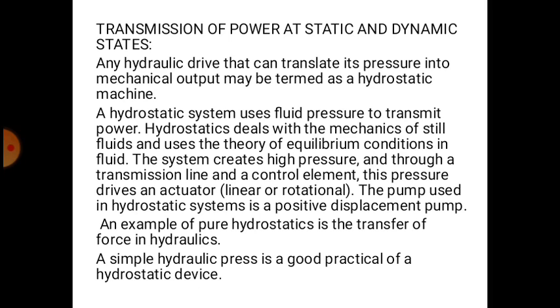In the fluid, the system creates high pressure, and through a transmission line and a control element, this pressure drives an actuator. The actuator may be a linear type or it may be a rotational type. The pump used in a hydrostatic system is a positive displacement pump. An example of pure hydrostatics is the transfer of forces in hydraulics. A simple hydraulic press is a good practical example of a hydrostatic device.